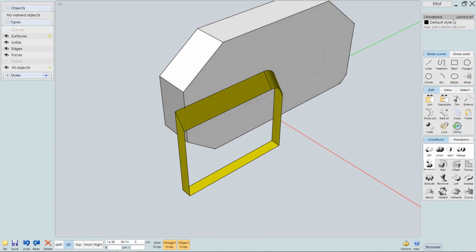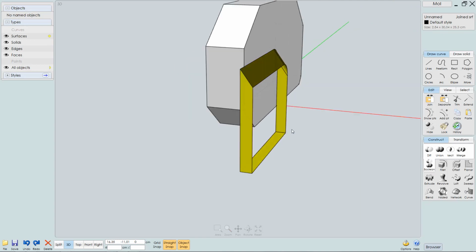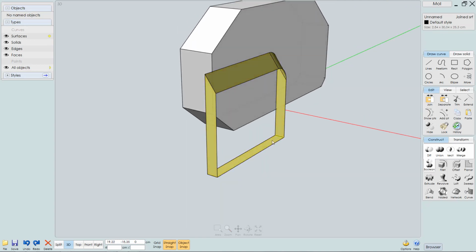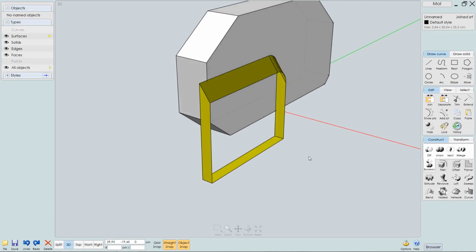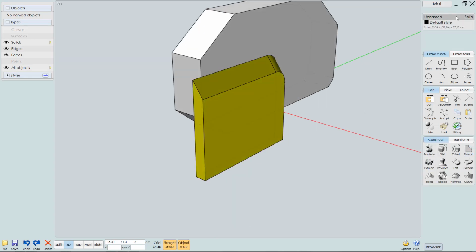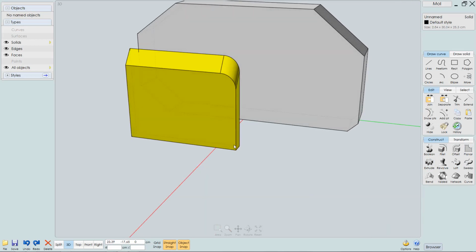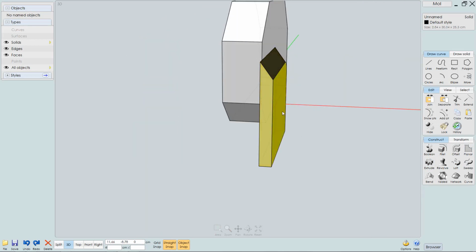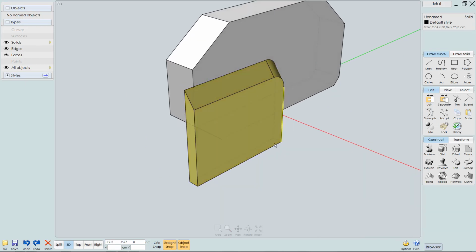And you can see up here that it's still just a joined surface, and in this case there's nothing wrong with the object except it has holes at the front and at the back, and we can close those by using the planar option under construct here. So this will turn this into a solid object. And because this extrusion is sitting right on top of the other shape, we can't use a Boolean Merge.